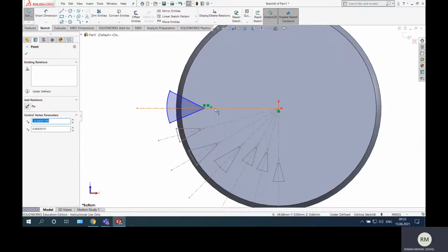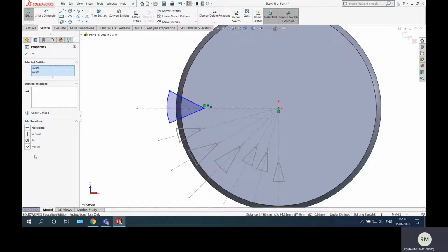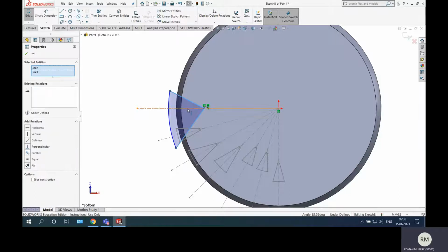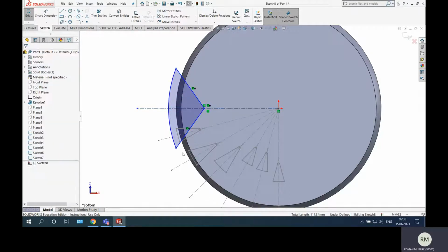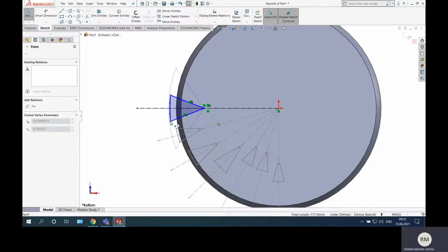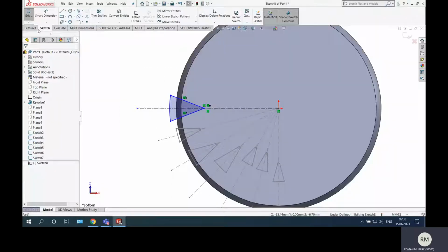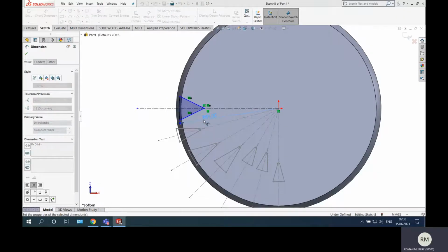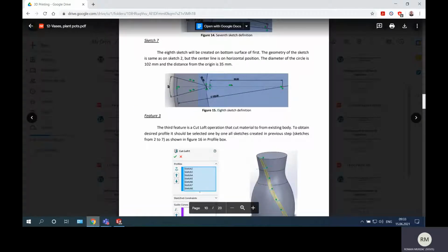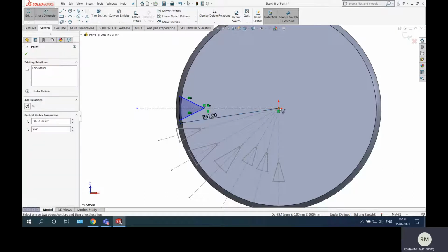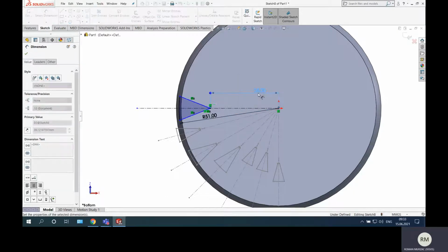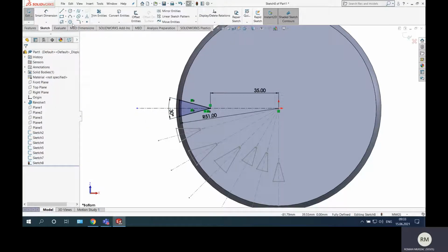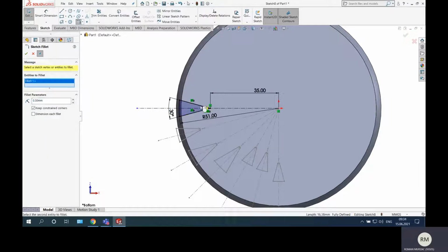This point with this point should be coincident, merged, and this line with this line about the axis should be symmetrical. Yes, and the dimensions: the arc has 51 millimeters, 102 diameter, so this is 51 radius. The distance of the point is 35, so from this point to this point is 35. 30 degrees. Yes. 0.5 here, of course.